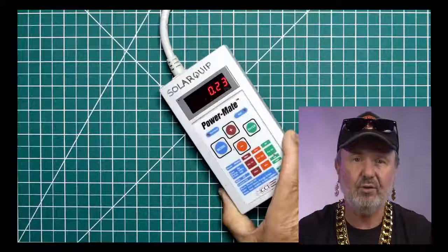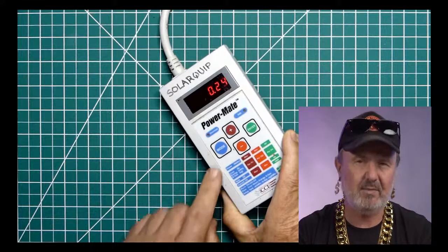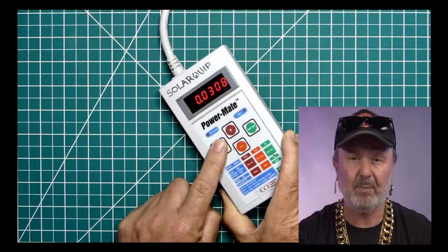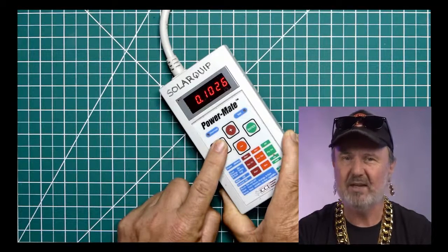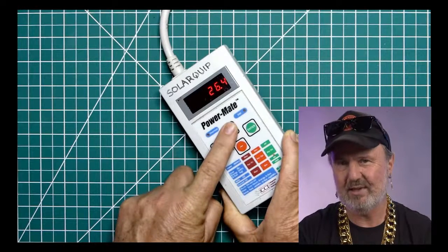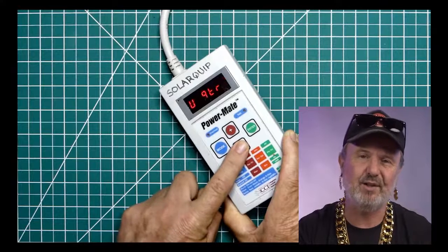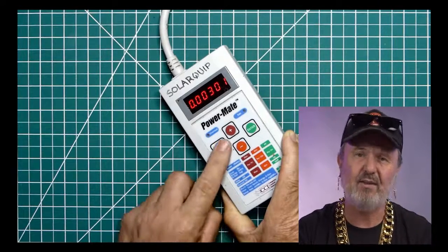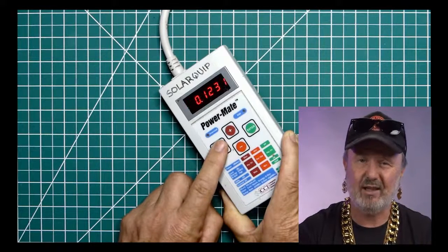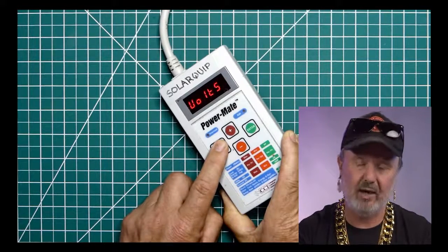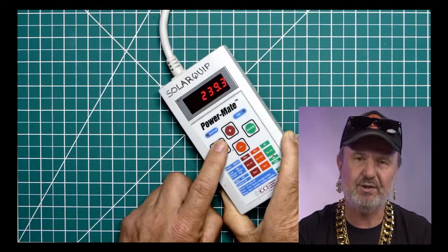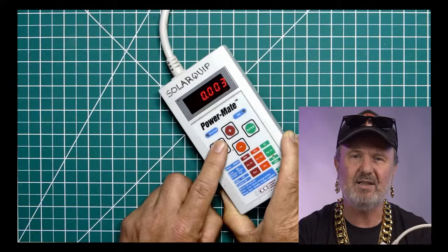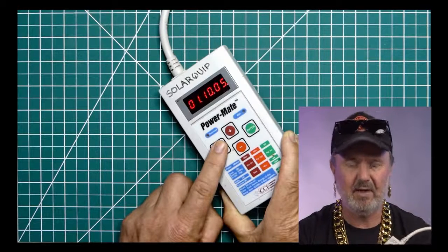It'll log that too, and it'll tell you, I think it's the 100 millisecond surge as something turns on, so it'll show you the peak, it'll show the average, it'll start to do kilowatt hour calculations, which is really great as well, especially for a fridge which cycles. But that peak that it measures is quite useful. So you're kind of measuring the relatively long inrush. 100 milliseconds is quite long, but it's certainly useful to know what that peak was. So that's kind of like a consumer appliance measuring device. Really recommend this particular one.